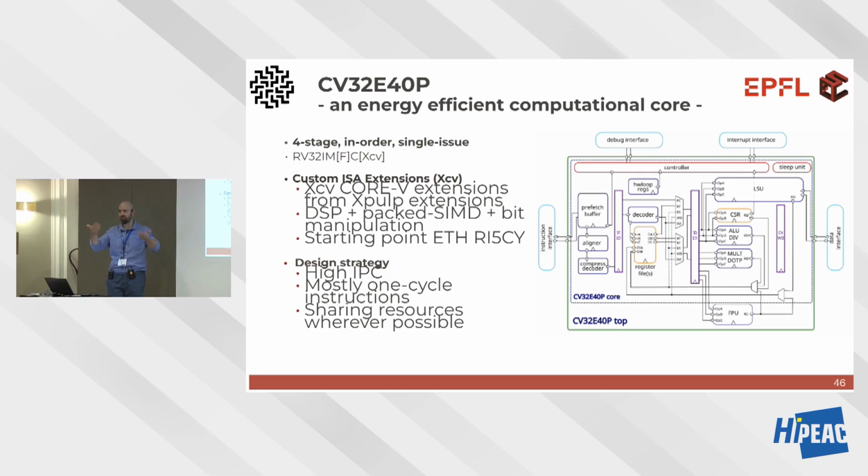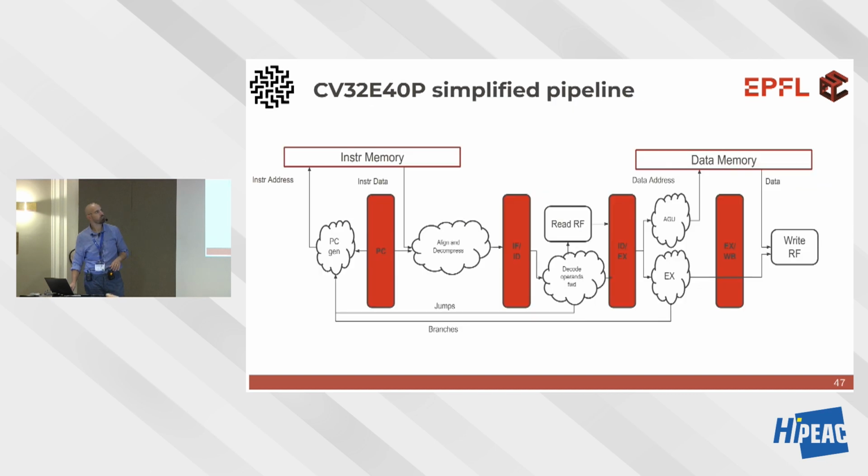But there is no other pipeline stage containing the operands, because there is no other pipeline stage. This one, yes. So if I'm not using one of those functional units, the operands there are not changing. They stay the same, reducing dynamic power, except for one bit, the enable. I have to tell the multiplier not to do anything when I'm not using it. Except for that bit, the other ones are gated.